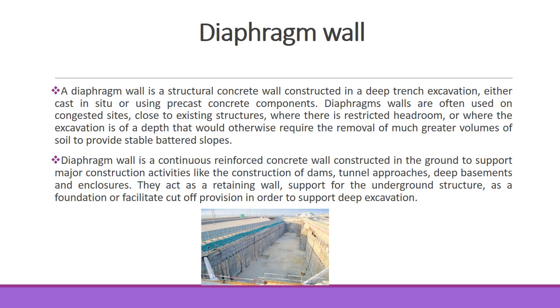So let us see the diaphragm wall. A diaphragm wall is constructed in a deep trench excavation. It is a structural concrete wall, either cast in situ or using precast concrete components. Diaphragm walls are often used on congested sites close to existing structures where there is restricted headroom, or where the excavation is of a depth that would otherwise require the removal of a much greater volume of soil to provide a stable slope.